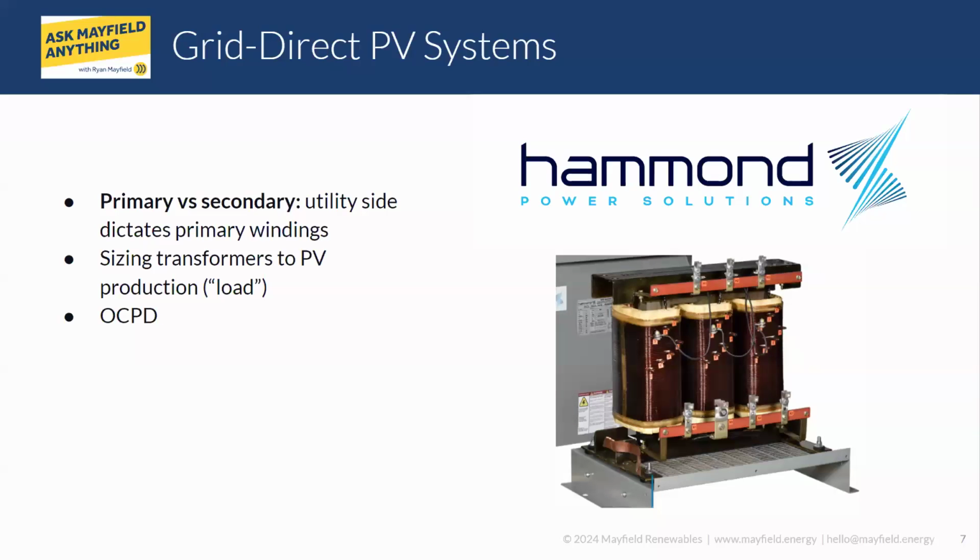Yep, thank you for that, Jeff. Kind of reiterating what he was saying, what it really boils down to is what side you are initially energizing. Once that core has been magnetized, then you are suitable for bidirectional use. For most utility interactive applications, the grid side energizes the primary, or outer winding. Once that core is magnetized, it will usually give the inverters the signal that the grid is there and present. Once that happens, power will flow and push back towards the grid. That's the main principle for grid side versus inverter side of the transformer.